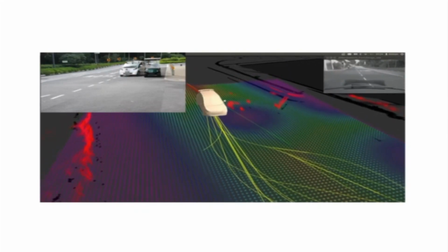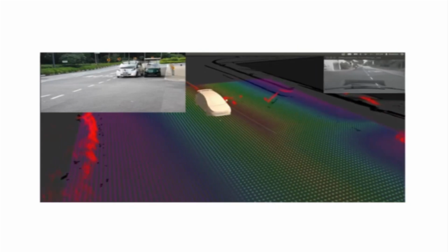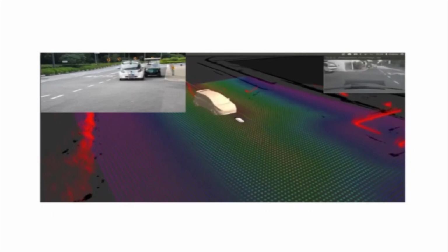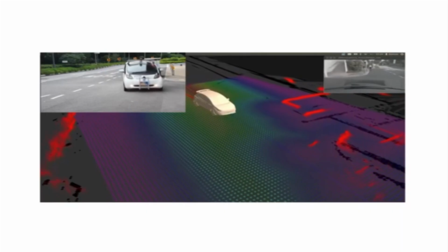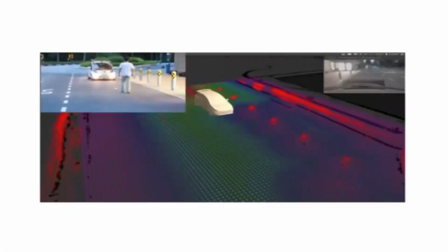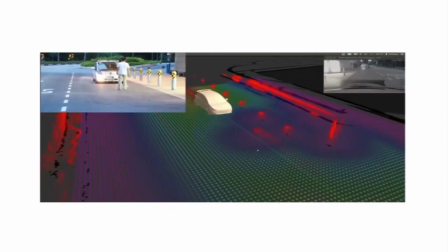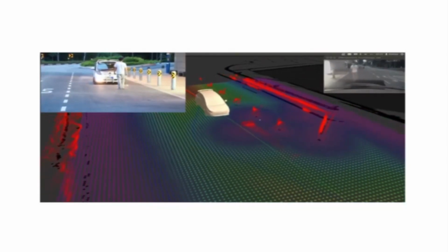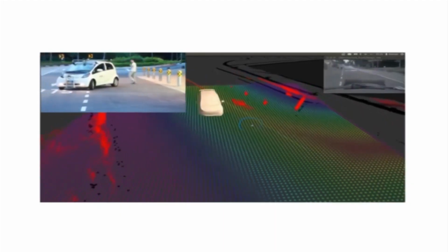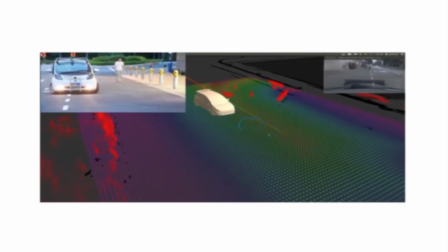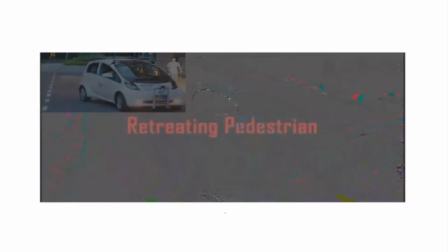Okay, so it has a LiDAR and a camera in front, and the simulation is shown here on the right side. So the moment it sees something in front, it will stop. It will find another path by shooting out another ray. Okay, so there is a pedestrian who is approaching. So you can see that immediately it will see. Okay, so that was the person. So it has changed its path exactly by using RRT, and then comes back again. Okay, so this is doing obstacle avoidance using RRT.